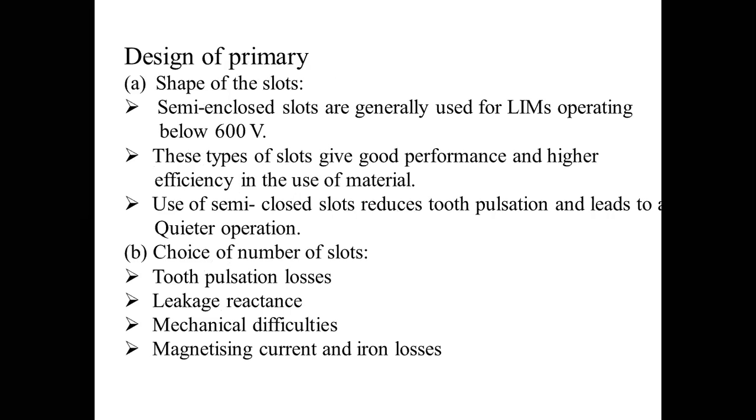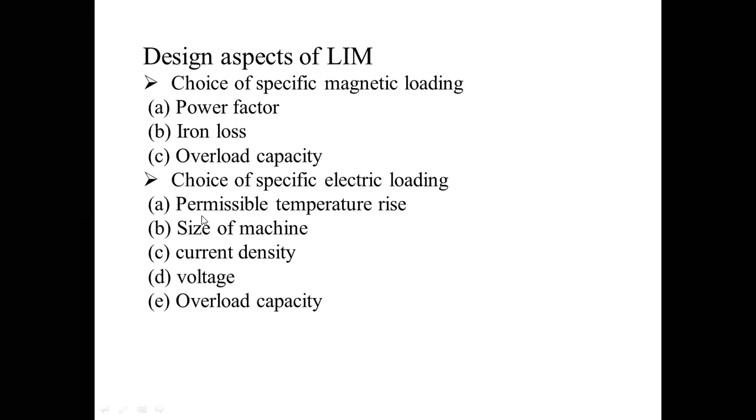On the choice of specific magnetic loading, we consider power factor, iron loss, and overload capacity. On the choice of specific electric loading, we consider permissible temperature rise of the winding itself, size of the machine, current density, voltage, and overload capacity. These two important parameters, specific magnetic loading and specific electric loading, we consider while designing any linear induction motor. So these are the important aspects.